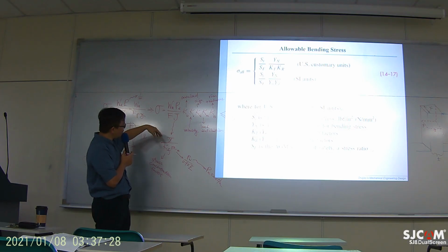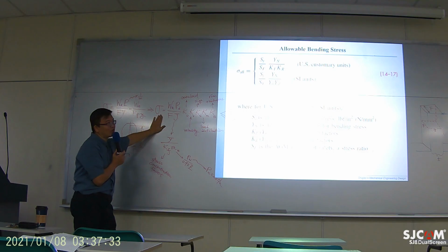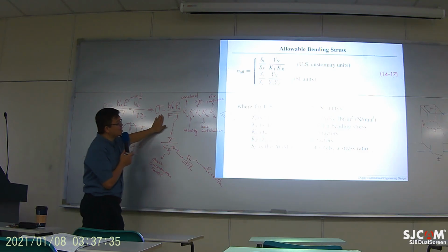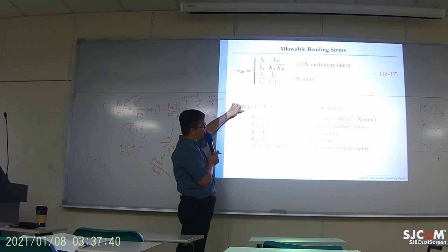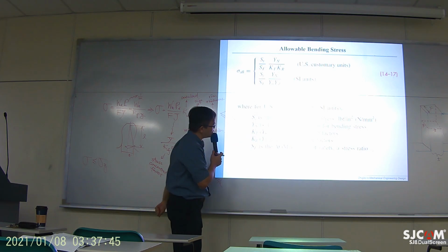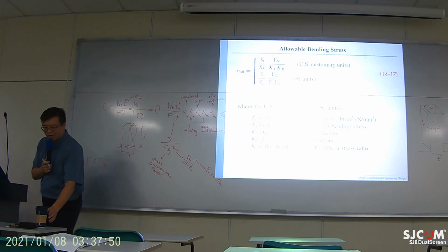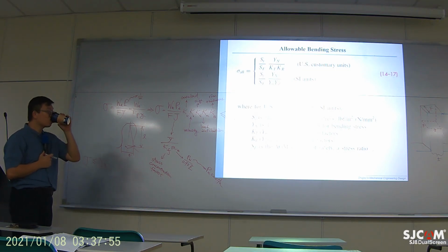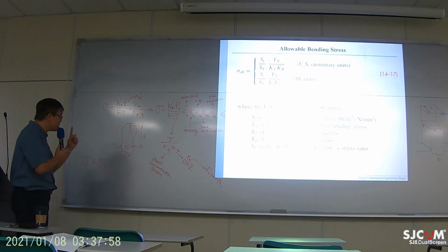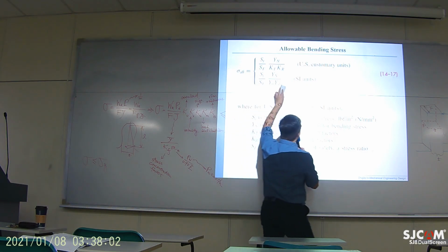You correct the estimation of the stress in such a way that you end up with a stress value that has to be smaller than your limit. The limit depends on your yielding strength, safety factor, temperature, reliability, and also cycles. So that would be the complete equation for tooth design. However, this is the first kind of failure for a tooth.